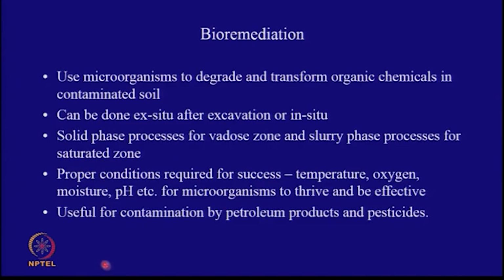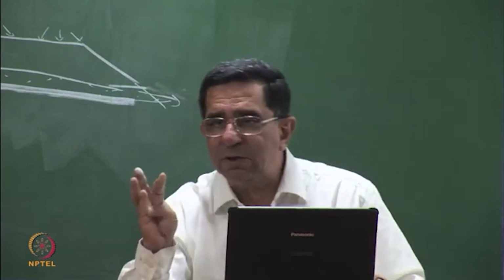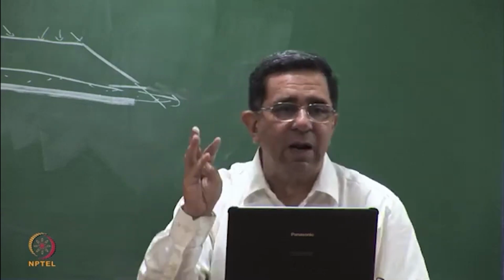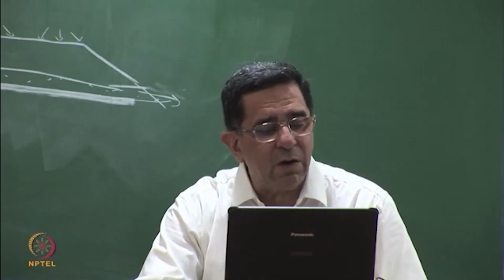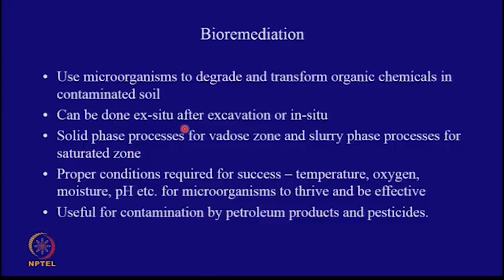Bioremediation. Well, basically you use microorganisms to degrade and transform organic chemicals in contaminated soil. And usually when you have petroleum products or hydrocarbons or pesticides, if you have overdosed it, you can introduce microorganisms. This can be done ex situ or in situ. Ex situ is much better because you can do it in a controlled environment. You can control your temperature, moisture, relative humidity, and available oxygen. So, better you bring out the soil, excavate it and do it in a containerized manner.